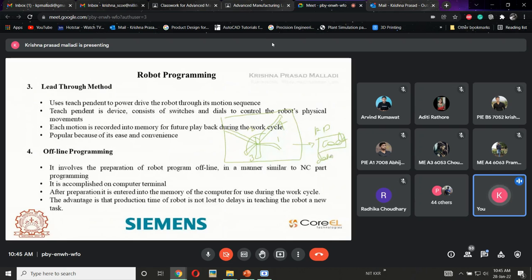I will collect this data script in a pen drive. The robot has a controller, so I will give that program to the controller. Just like a pen drive, in the controller we have a menu. In that menu I open the pen drive section, and in that section there is a program. For the first program I'm going to test run it.